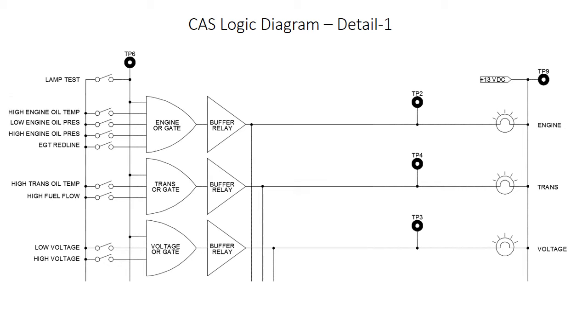And so by doing the math and doing some flight testing, I was able to come up with a fuel flow limit which will approximate the torque limit on that input shaft. So that's what I'm doing there. For the third channel, voltage, I'm looking at both high and low voltage warnings. So that's the way that I'm cutting down on clutter, taking those 8 inputs, reducing them to 3 alarm outputs.